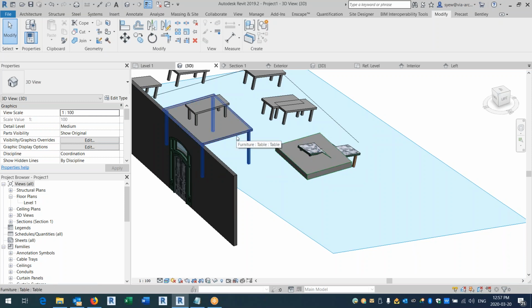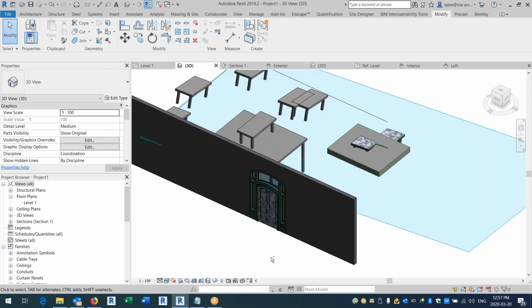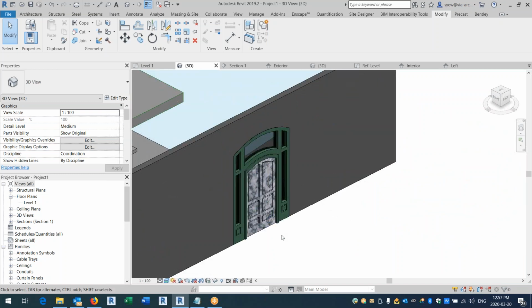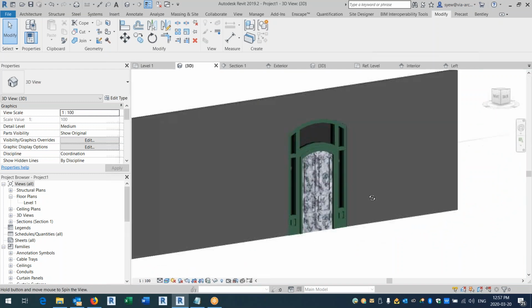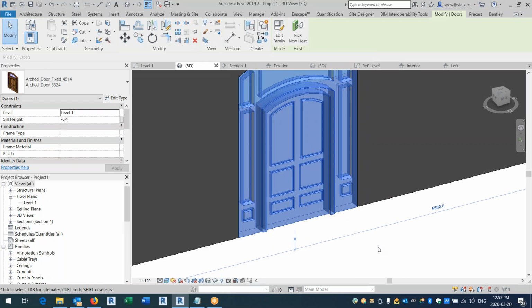Also, always add in a reference plane, because a reference plane will save you a lot of time when it comes to like a skeleton, to flex how you want it to flex, and then have the model attached to the reference plane. The next thing is that if you have models from existing ones, you can always go in there and modify stuff so that you don't have that particular issue.